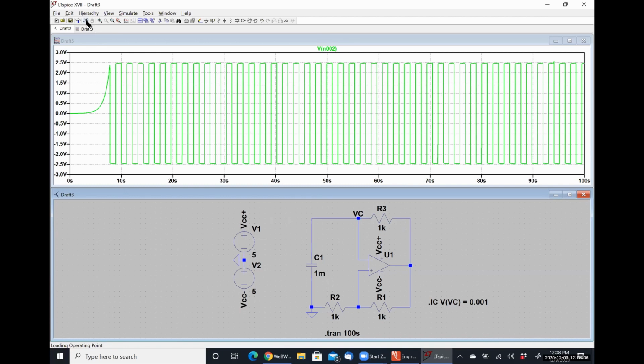So putting initial conditions on things, when you're doing homework regarding transient analysis, this is exactly how you can do it. You can draw the circuit for t equal to 0 plus and beyond, and put the initial condition on your capacitor voltage and or inductor current, and it will plot the transient analysis, and you can literally type out the mathematical function and make sure that they overlap each other to check your work.